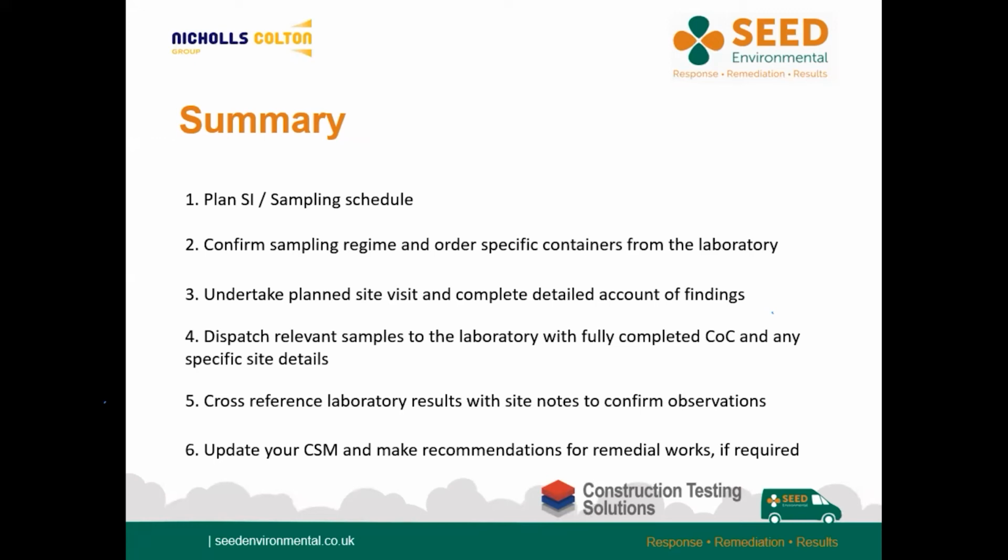Once the site investigation has been completed, or if your phase of works is extended over several days, you will need to arrange for regular sample dispatch to the laboratory to avoid the risk of deviation and to allow the sample results to be returned in a timely fashion. When you dispatch the samples, send a completed chain of custody, and as Amy mentioned earlier, make sure that you contact the laboratory beforehand if you require a faster than standard turnaround, or if you consider your samples to be heavily impacted and will therefore require some additional preparation before being tested.